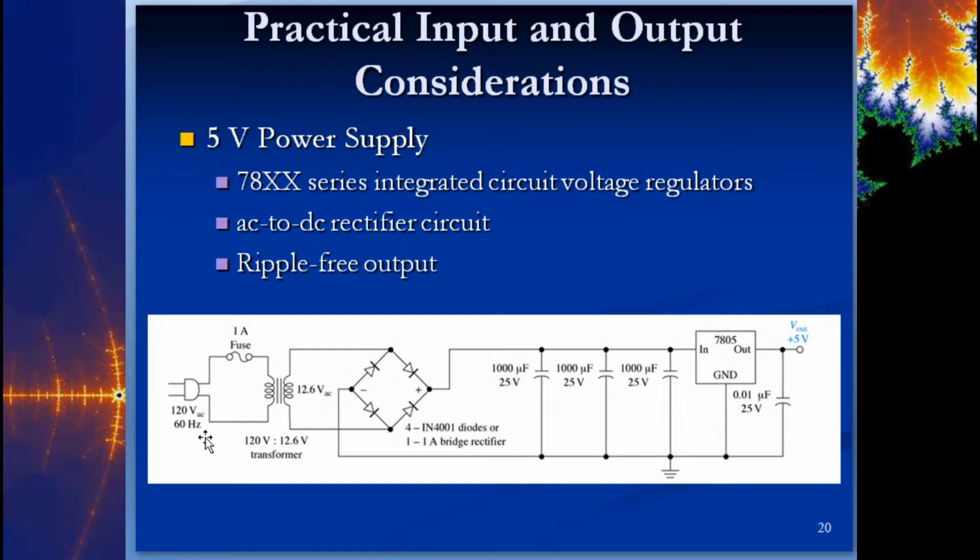And sometimes if you take your laptop to some other country where they have a different plug and also a different frequency, you have to put a little adapter on your plug, because you can't run an American-made device on 50 hertz. You'll destroy it, or you'll burn out at least some of the components. So anyway, 120 volts, 60 hertz, that's what comes out of the wall here.